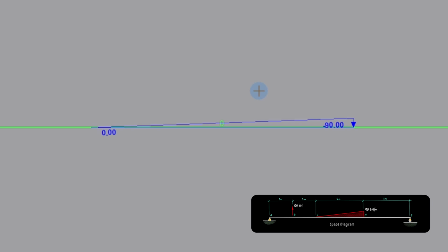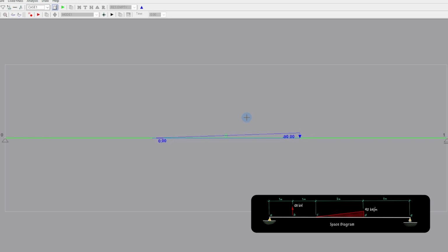Yes, really. Dr. Jim hopes an alarm bell has gone off in your head. A downward load of -90 is the same as an upward load of +90. To fix the diagram, either the negative sign should be removed or the arrow should be turned around to point upwards. Think about it. LinPro is good, but it's not perfect. Dr. Jim's advice is to ignore negative values on all graphical representations of loads and reactions. It's annoying, but just live with it.